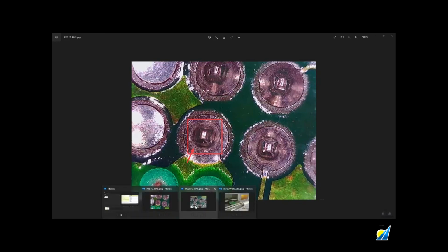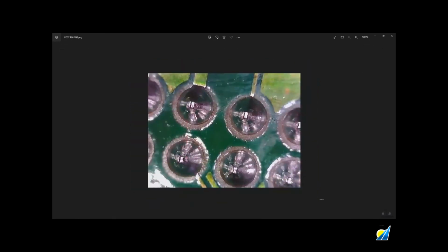Now post-fix, this is what they should look like after the solder's been reflowed, and AC Tronics have done a marvellous job here. They use a technique called vapor phase soldering, I think it's called, where they heat the instrument panel PCB up and reflow the solder. But as you can see here now, no cracking around the pins, so this is post-fix. Pin contact with the solder as well. And these are taken, I'm not sure if they're under a microscope, but they're certainly zoomed in.